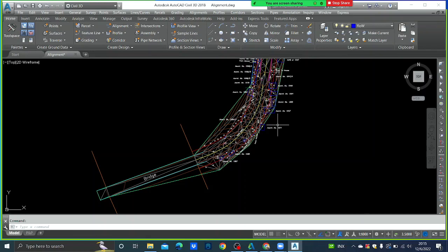Our usual design speed in national roads is either 70 kmph or 50 kmph, because in rural areas it is 70 kmph, and in urban areas it is 50 kmph.